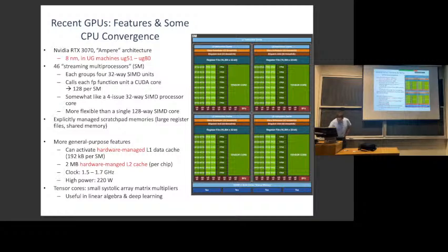The last thing it has here, which I'm not going to talk about, is Tensor Cores. Who knows what a Tensor Core is? Have you ever heard of this? Okay, so Tensor Cores are little matrix multiply units. They're built using a data flow architecture, like a streaming architecture that's called a systolic array. So data kind of streams in all the time, and they're multiplying 2 little matrices. Usually, I haven't checked this generation, but the previous generation, it was like 4 by 4 matrices.